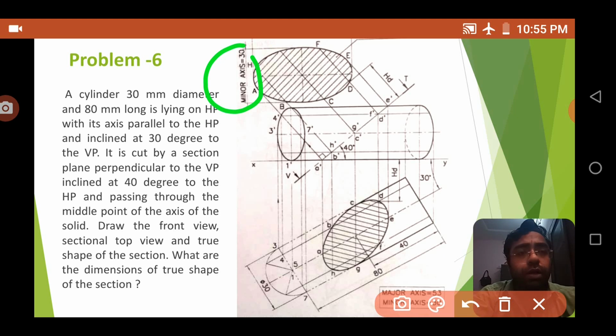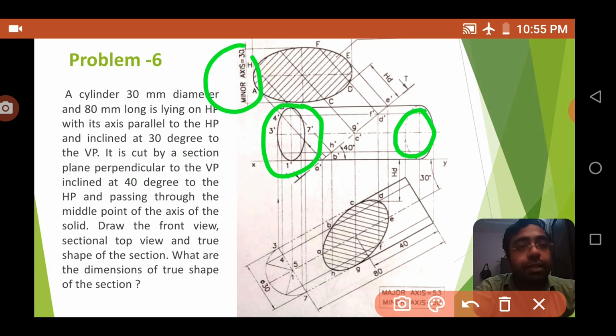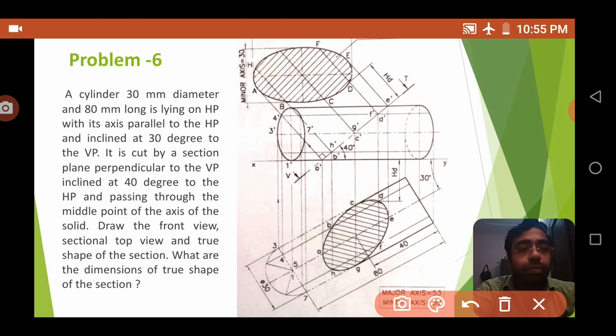In this one now we will think about the rewrite, about this line, which of the lines we have to see here. This part is visible, so we mark it with continuous thick lines. But inside here, on the other side it is coming, so you can see this is invisible, I mean we cannot see that side. So we will use continuous thin dashed lines.